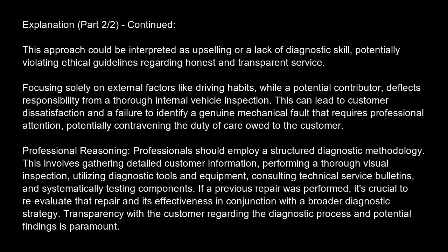Professional reasoning. Professionals should employ a structured diagnostic methodology. This involves gathering detailed customer information, performing a thorough visual inspection, utilizing diagnostic tools and equipment, consulting technical service bulletins, and systematically testing components. If a previous repair was performed, it's crucial to reevaluate that repair and its effectiveness in conjunction with a broader diagnostic strategy. Transparency with the customer regarding the diagnostic process and potential findings is paramount.